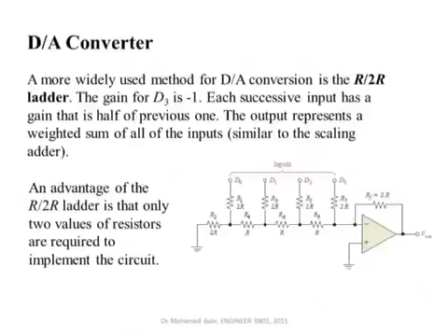I will show you that through an example, but what is happening here is that for every applied voltage, you can use a Thevenin equivalent. For example, if I make D0 equal to logic 1, meaning say it's 5 volts, I can use a Thevenin equivalent to replace all this part to the left.